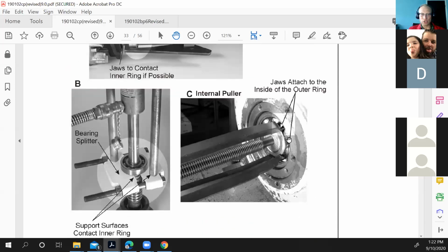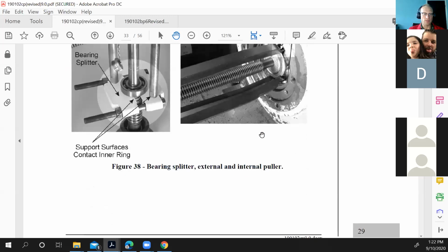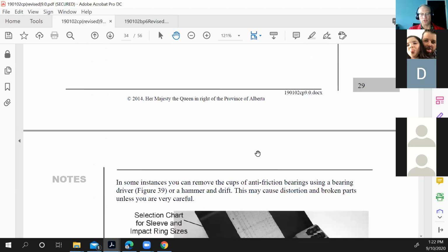This one, this internal puller, this is how you can change countershaft bearings without taking transmissions apart. Pretty common. Auxiliary boxes, same idea. Might end up doing something like this. That's where I've seen these. These I've seen in smaller agricultural applications, where I've seen shafts like this where you're removing bearings, but not so much in on-road tractor trailer stuff.